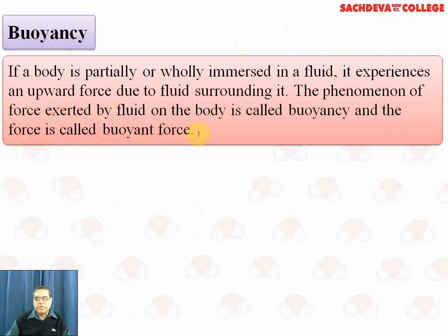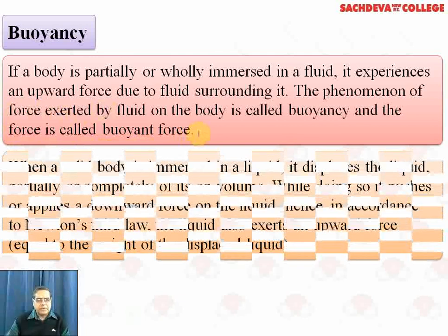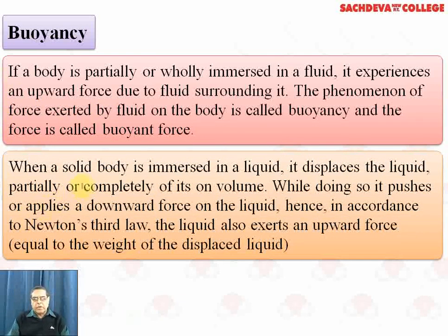So, buoyant force is within the liquid, and it is the force acting on a body in the upward direction exerted by the fluid or the liquid. When a solid body is immersed in liquid, it displaces the liquid, partially or completely, equal to its own volume. So, the liquid displaced by the solid will be equal to its volume. That is the law of flotation.